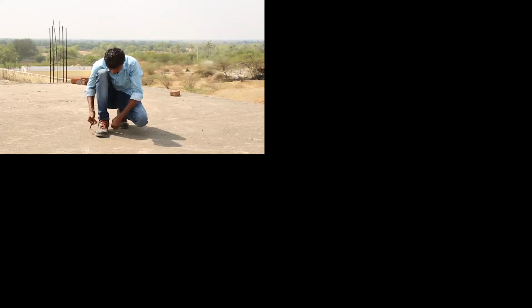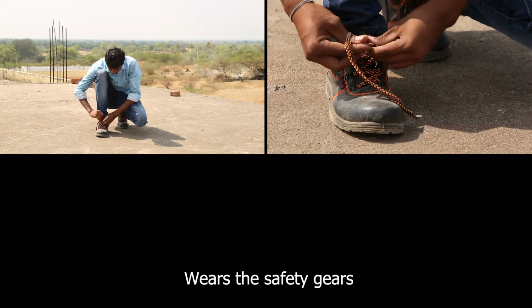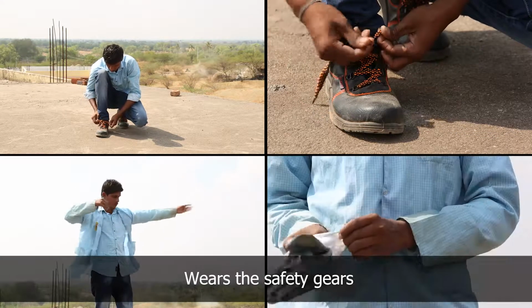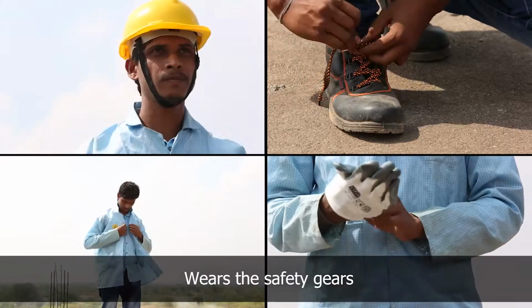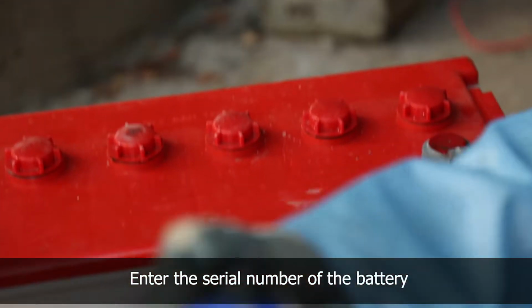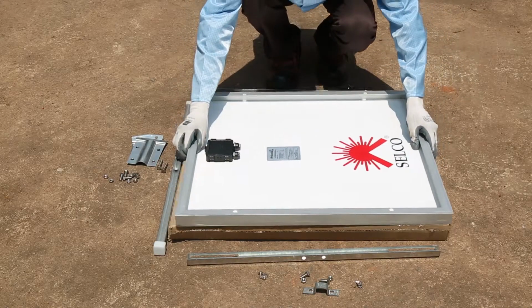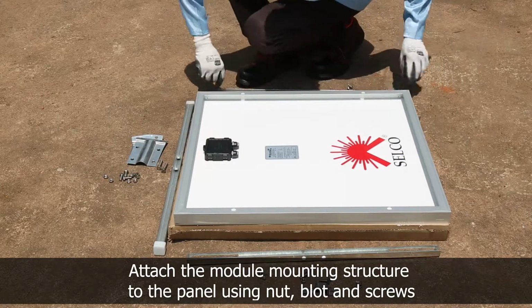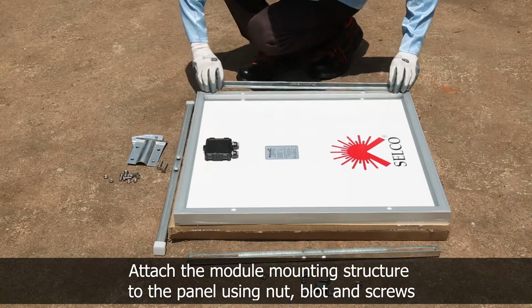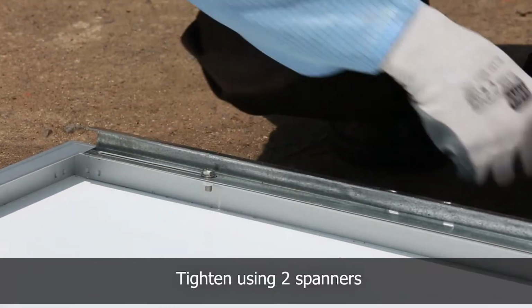The technician prepares for the installation. He wears the safety shoes, jacket, gloves, helmet. Enter the serial number of the panel and battery for warranty. Fix the module mounting structure to the panel using nuts, bolts, and screws with the help of spanners.